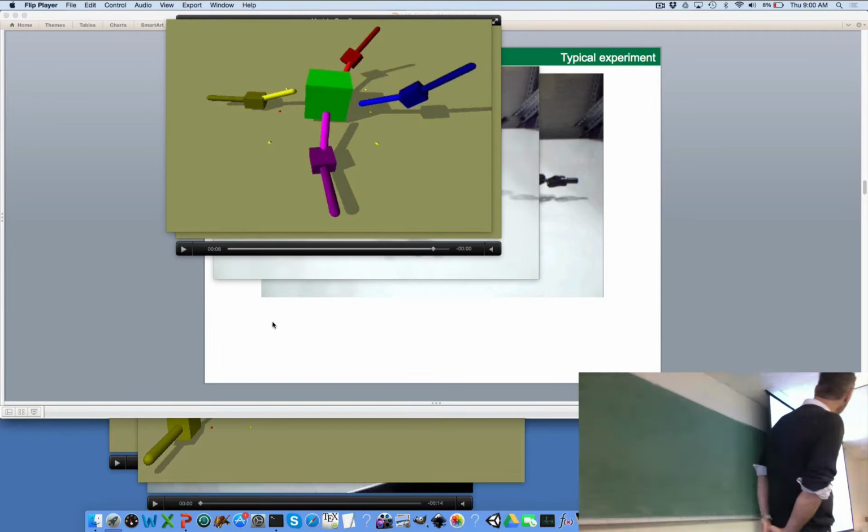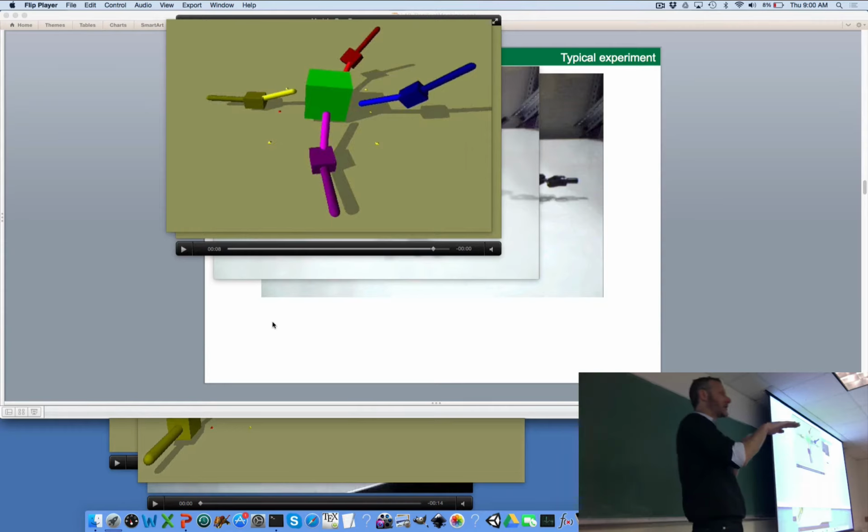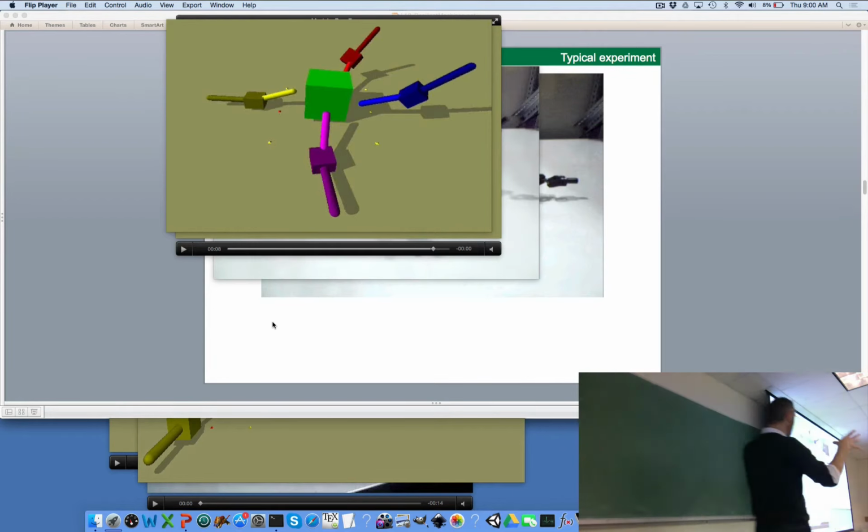Might be hard to see from this picture, but the upper and lower legs are bent a little bit, right? They're not perfectly straight. And that may just be, if we kept running evolution, maybe it would have straightened the legs. I think that they're bent actually because it's trying to reflect the mass distribution of the physical robot. The mass distribution of the physical robot is not perfectly symmetric, and we did not give the robot the ability to evolve the masses of each of these individual pieces. But by changing the geometry, the rotation of these pieces slightly, it might be able to slightly better match the mass distribution of the robot.